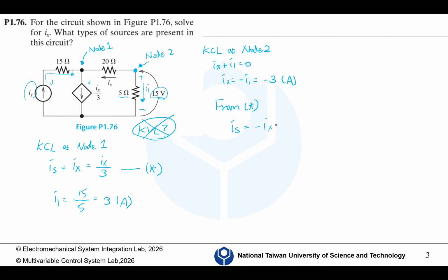So let me double check if these equations are correct. 70, 20 (I1 minus I3), 10 (I1 minus I2), and then 10 (I2 minus I1), plus 12 (I2 minus I3), plus 42, and then 20 (I3 minus I1), 12 (I3 minus I2), plus 14 I3. So this is correct. And then you just need to solve the problems on your own.